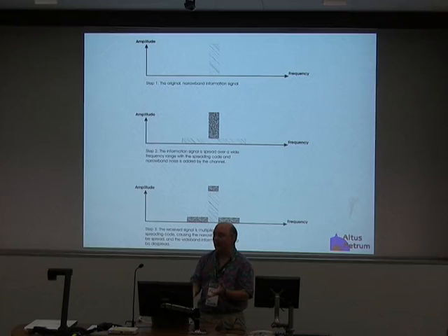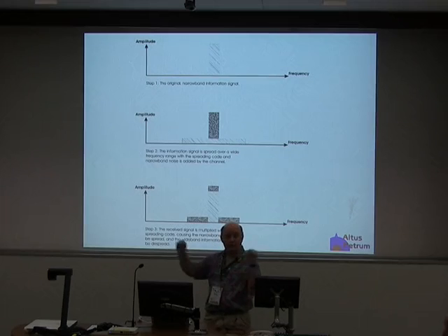You start with this narrowband information signal, and then you multiply it by this, or you XOR it with this really high frequency pseudo-random sequence, and you smear your signal over a huge swath of bandwidth, but the amplitude is lower, right? Because you've taken your signal and divided it out over a whole much more space. And so your amplitude is lower.